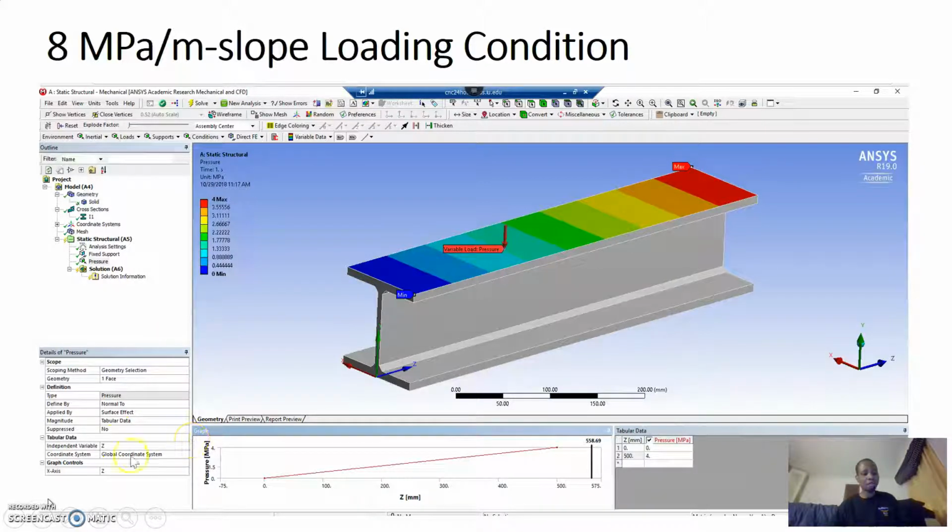I did my loading condition in ANSYS by choosing the option of the tabular form when I'm applying my pressure. The tabular form gives me the option of varying my pressure at every point. So my pressure is not the same at every point.